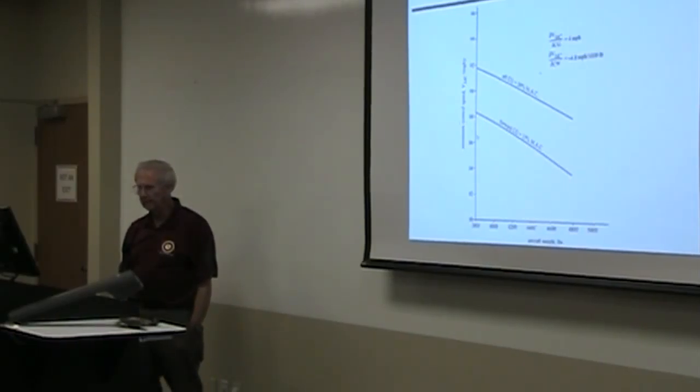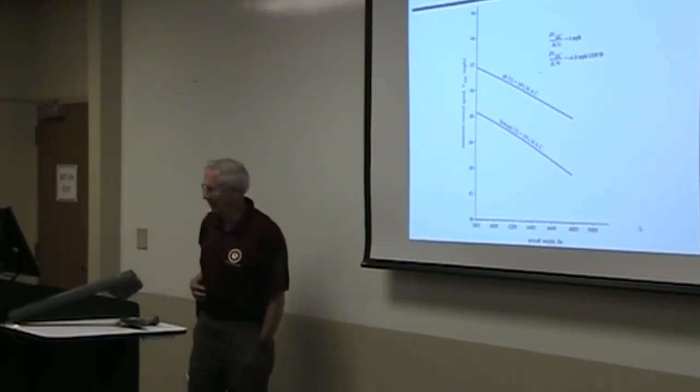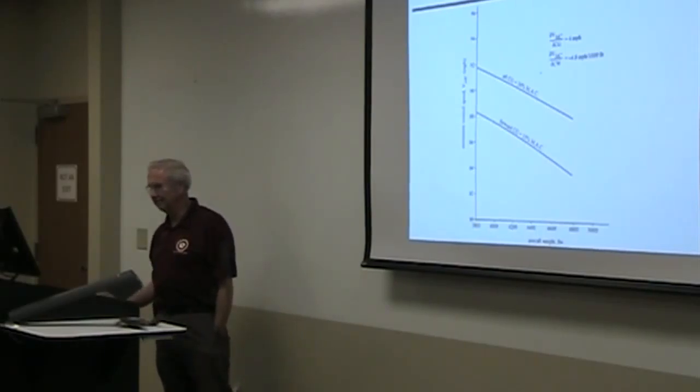But if you're at forward CG at lightweight, you're above that speed. Notice that it's about 89 miles an hour at lightweight, even at forward CG. At aft CG, looky how high it gets. You know, here's the number that got published. And there's what's happened if you let the airplane get light.